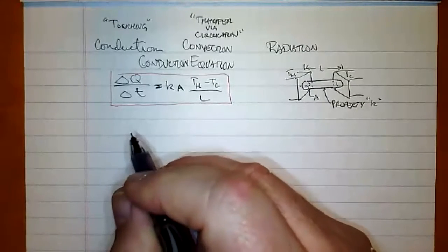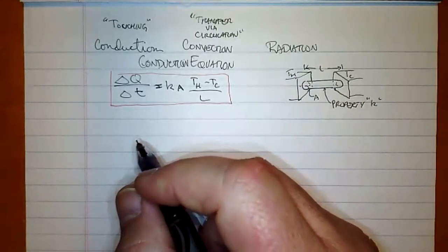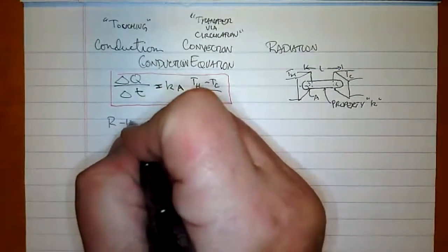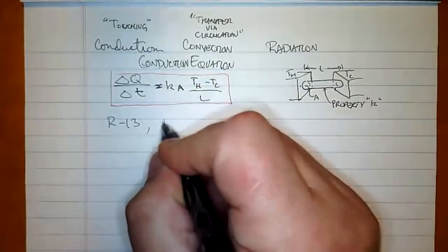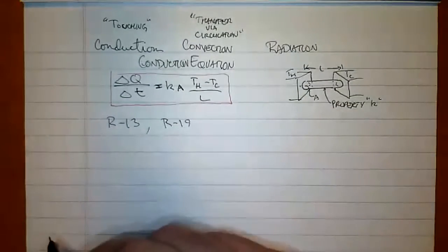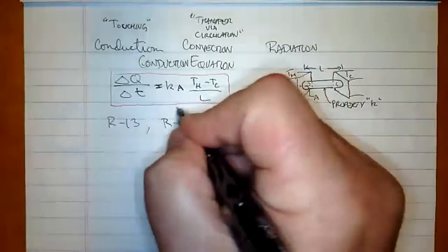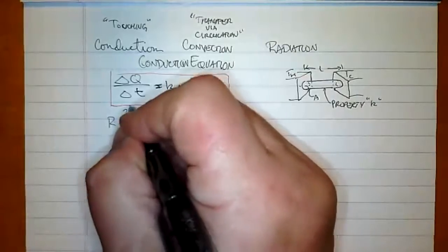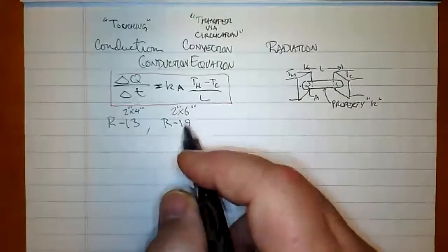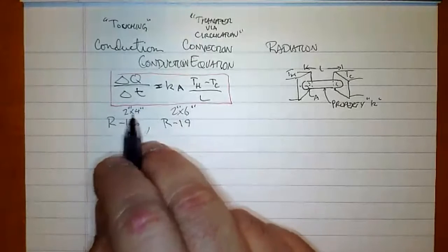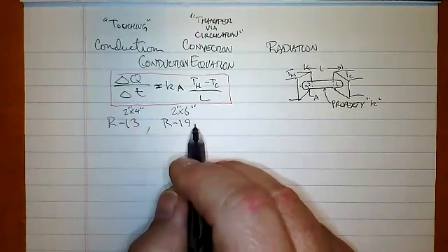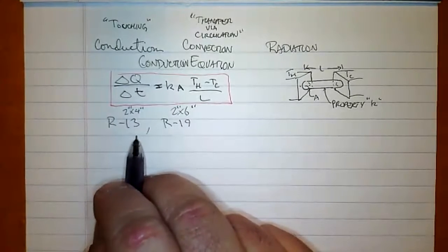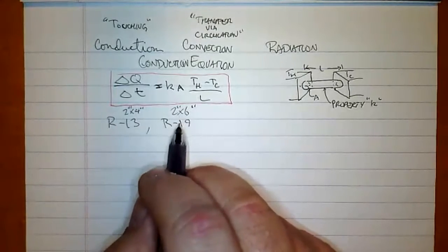If you go into a house and it's being built, you'll see that there's bats of insulation on the walls, and they'll have like R-13, or in some higher quality houses, you'll see R-19. And that's houses whose walls are 2x6 construction. And this is a house whose walls are 2x4 construction. If you want your house to be better insulated, you do not want to take your 2x4 walls, pull out the R13 and put in R19, because you'll actually make the R19 less than R13. So don't do that. It's the air that's trapped in the insulation that makes it so valuable.